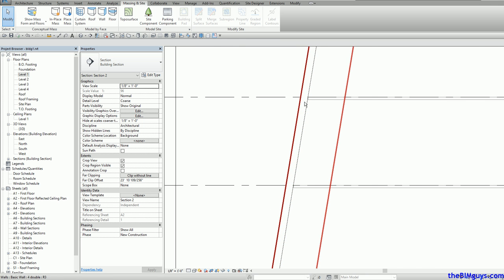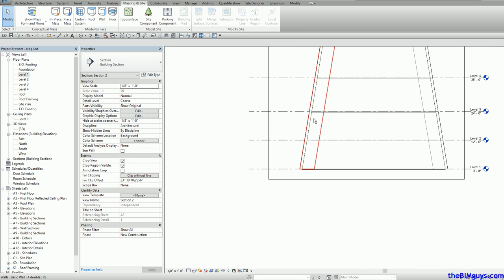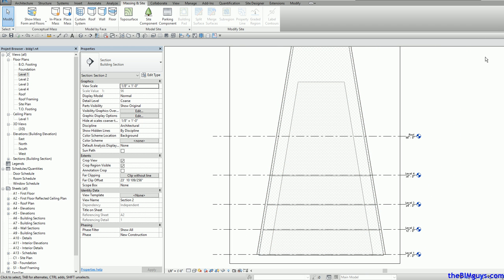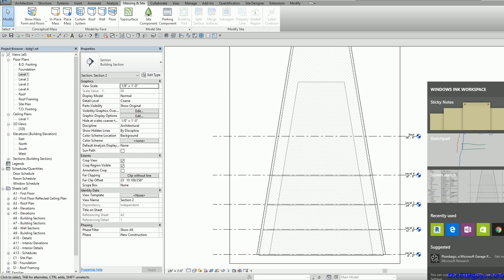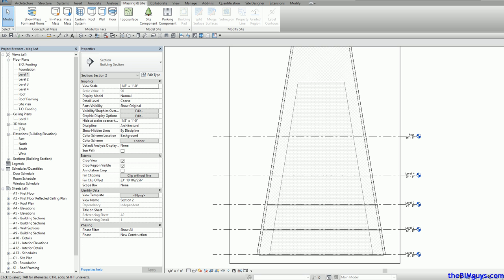Since we told Revit that we want the floor to stop, well, our walls to tie in on the face of that, that's how it knows where to place them. You have to play with that a little bit to get exactly what you want. But that is important to make those things happen. I'll go back to that. And in here you'll notice that there's the edge of the mass. And then we added one wall outside, a wall inside. So it got a little heavy, but that's how you make all the walls really start to refine each other.